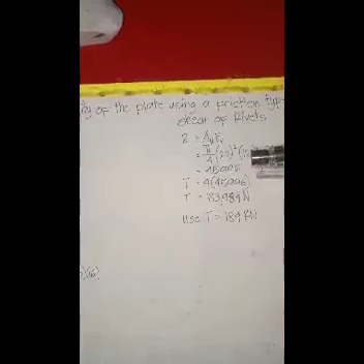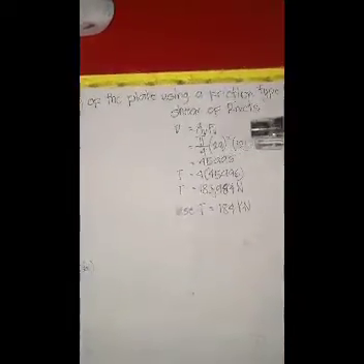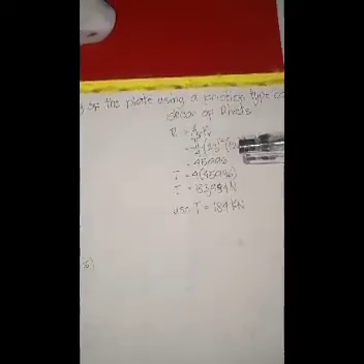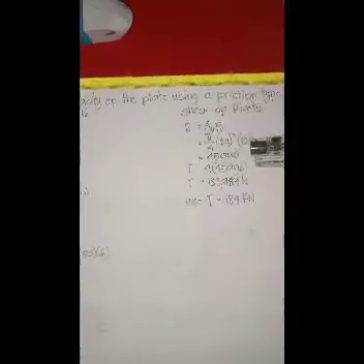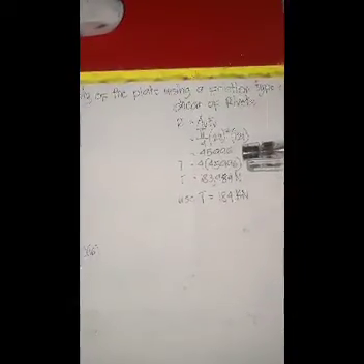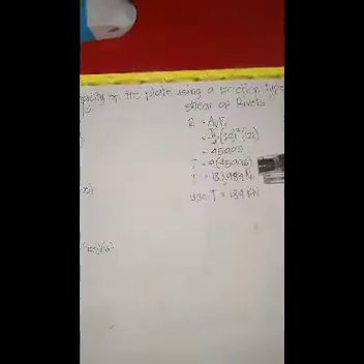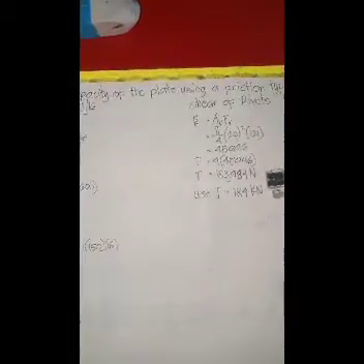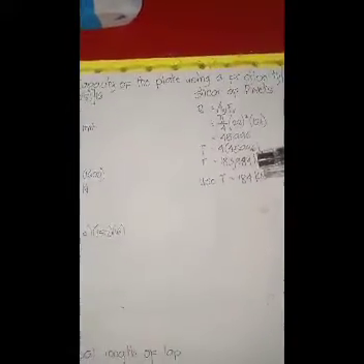Then substitute pi over 4 times 22 raised to 2 times 121, the value for friction from the given. Then 45,996 Newton times 4 again because there are 4 bolts. So our tensile capacity for all bolts is 183,984 Newton. Then we take the smaller one as the tensile capacity.